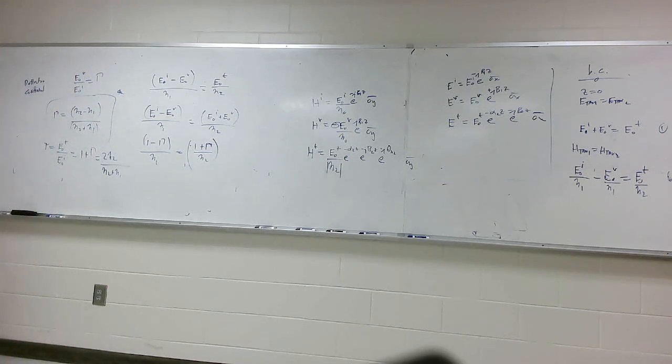Do you remember this from transmission lines? Remember with transmission lines, we didn't have eta, we didn't have characteristic impedance, we had actual impedance as Z, right? And the reflection coefficient with transmission lines is the impedance you're going into minus the impedance you came from over the sum of the two. Here, it's the same exact formulation, only these are intrinsic impedances, not actual impedance values. So here, it's eta 2 minus eta 1 over eta 2 plus eta 1. And the transmission is just 1 plus reflection coefficient for normal incidence.